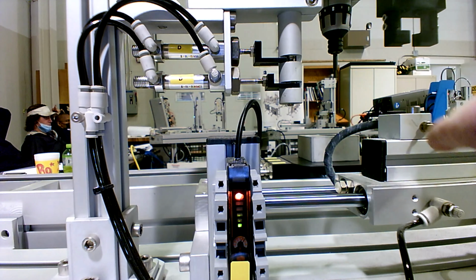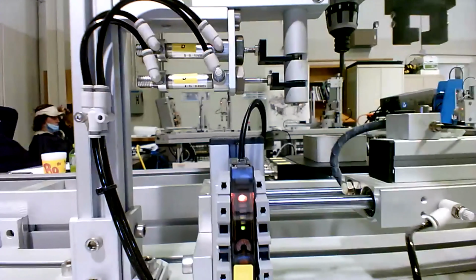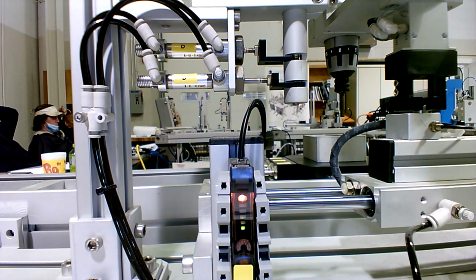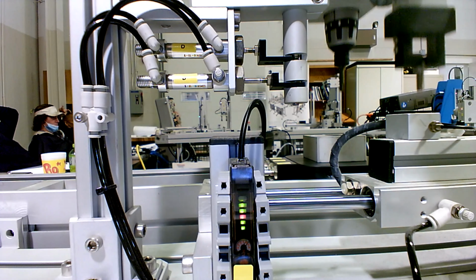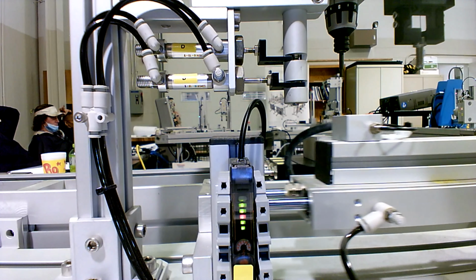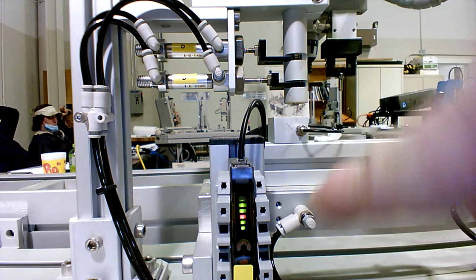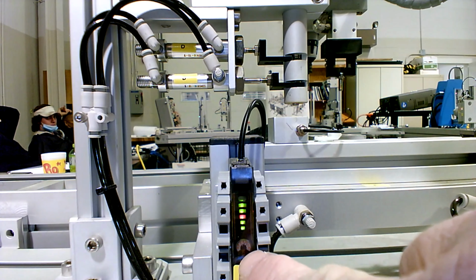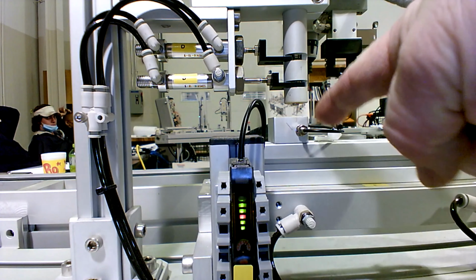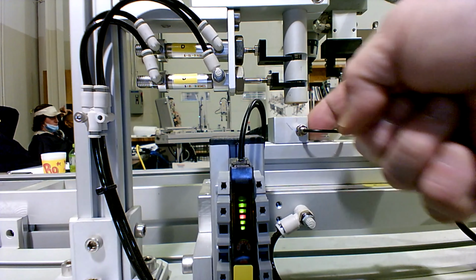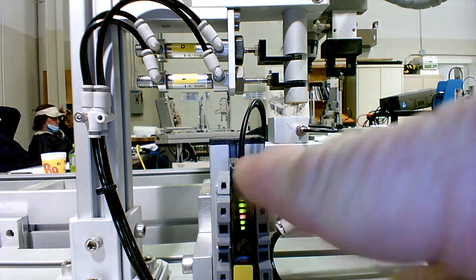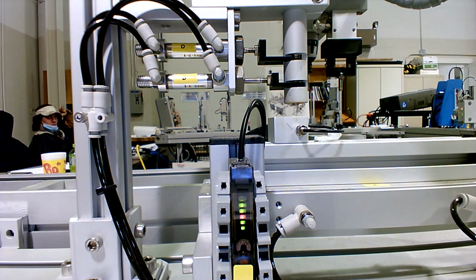So now we're over here looking at this, where it's going to come get it. I'm just going to jog it through. Come down, get it, go. So what do you see on the module now? They came back on and the hole is clear because, you know, the fiber can shine through. And so the module knows it's receiving light from the transmit cable line, okay? So it sees it. And the PLC is getting a signal down here.